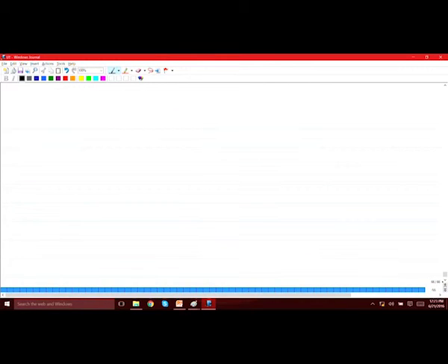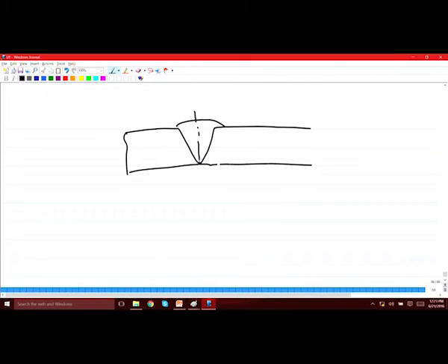Okay. So, if you have any defect inside the weld, let us say over here or over here, then when you keep the probe at the half skip, it goes to the root, and then as you move away from the half skip, let us say in between half skip and full skip, it can go and encounter these defects inside the weld. And the moment it encounters this defect interface, as I have said before, it will reverse the direction and come back to the probe, and that is how you will see the defect echo with respect to the half skip distance.